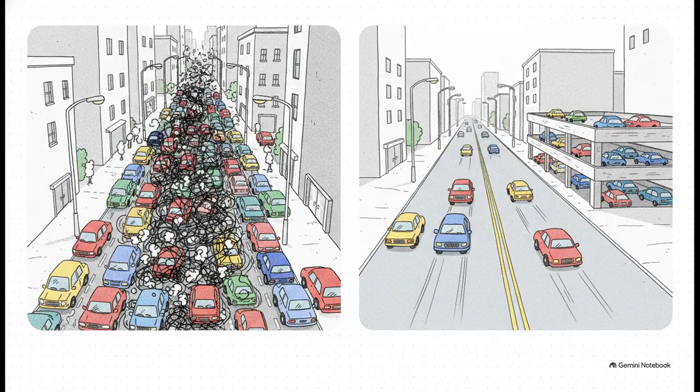But you know what the biggest choke point in these arteries actually is? It isn't moving cars, it's stopped ones, parking. Planners measure parking using equivalent car space, or ECS, and on-street parking is an absolute nightmare for urban flow. It eats up incredibly valuable road capacity and causes massive rippling congestion. That is exactly why modern cities are starting to price street parking incredibly high. The whole goal is to force drivers toward off-street parking, like multi-level car parks or underground garages, keeping the main arterial roads completely clear for smooth transit.